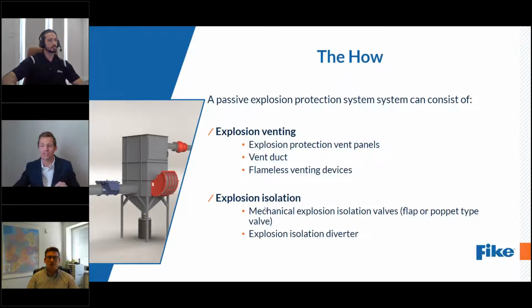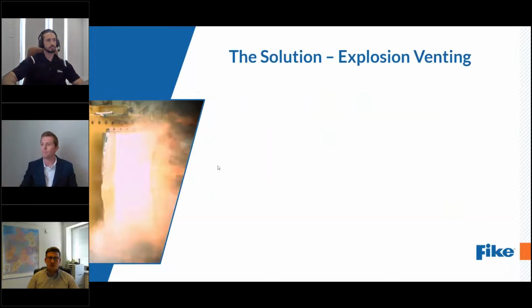Additionally, there's explosion isolation that's required to keep the explosion in the one risk area. You don't want it to be propagating back upstream, consuming a bunch of fuel, or you break a bag or something in a filter and it goes down the clean side, and now you're directing fireballs towards people at process equipment and what have you.